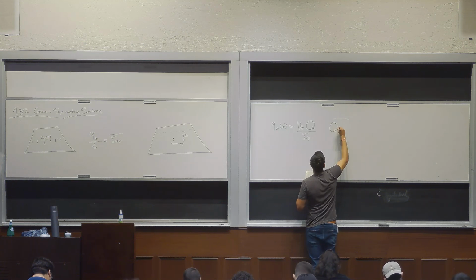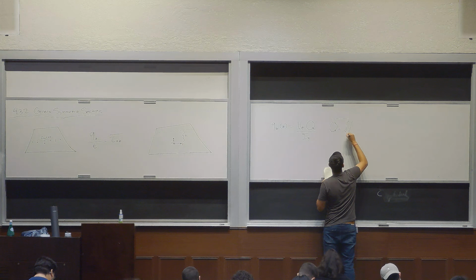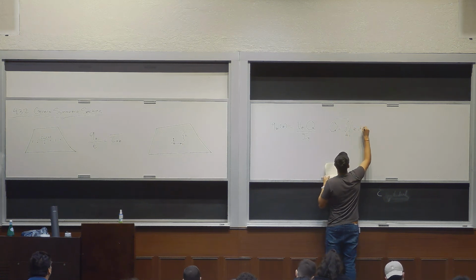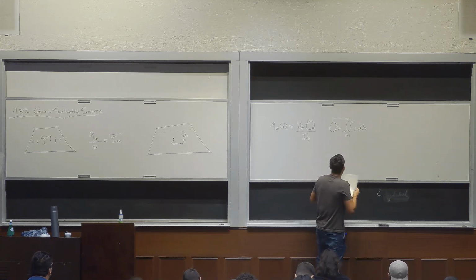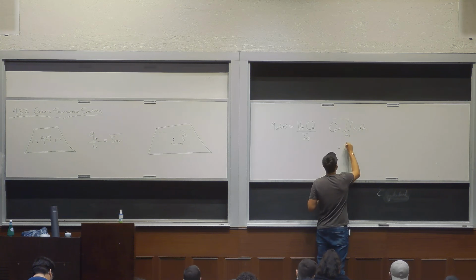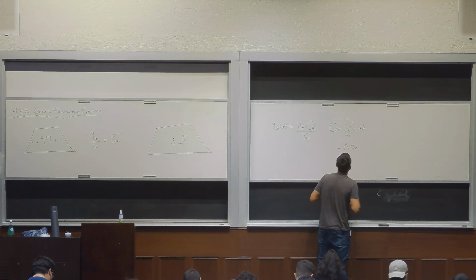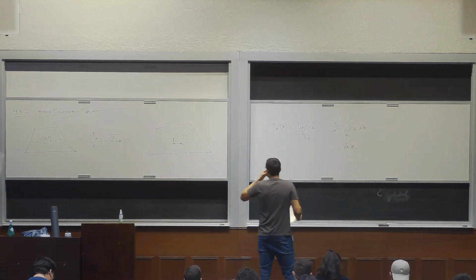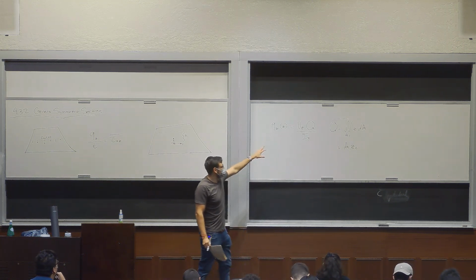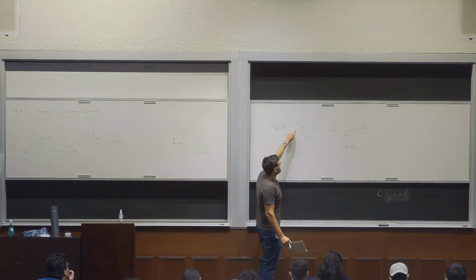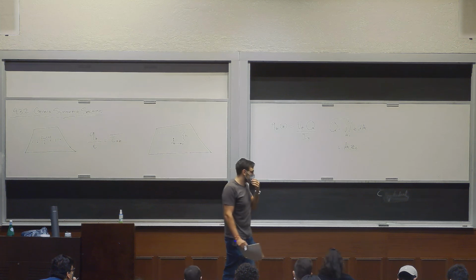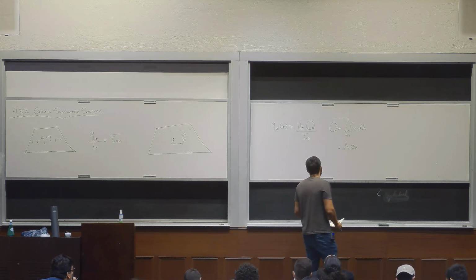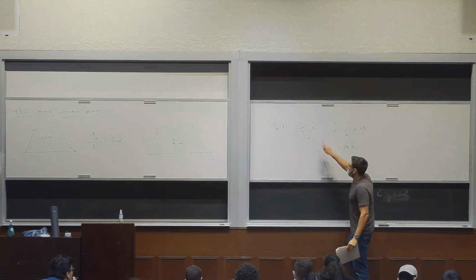Q, in general, is defined as the double integral of z dA. But as you may have noticed now in this class, anytime there's integrals, you don't really have to do any integrals. So typically, for these problems, you just multiply an area by the position of the centroid. So let's call it A1. That'll make sense in a bit. So we're trying to find QZ at a certain location Z. We would be given the shear force, and we could figure out the moment of inertia about the y direction, just based on the geometry. We've done plenty of examples doing that. Now the main thing for these problems is finding this Q.